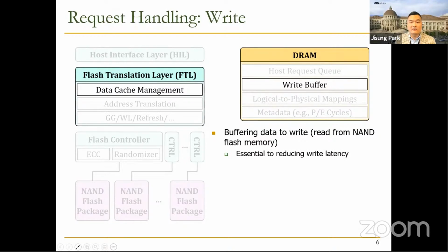The write latency of a modern NAND flash chip highly depends on the chip's technology, but a page write generally takes about several hundreds of microseconds. So without a DRAM buffer, and if all the NAND flash chips are busy handling previous write requests, another write must wait until the NAND flash chips finish the ongoing requests, which can expose the long write latency to the host system.